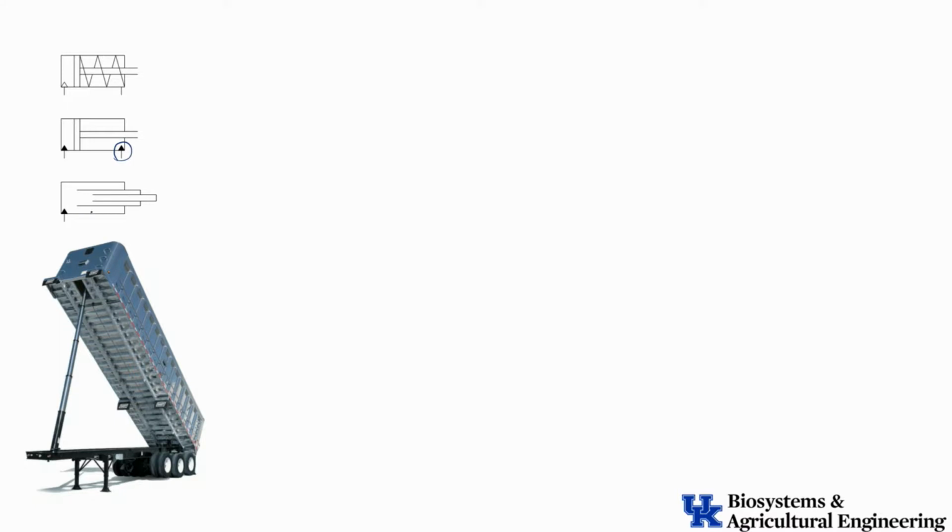It would be way too tall to put on the truck. So what we do is use a telescoping cylinder. You can see there are different diameters of the different sections of the cylinder coming up there. As we lift this thing, we put fluid in the bottom, and it's going to push each stage out sequentially. Obviously, when the first stage is going out, we have the most cross-sectional area. So think of the pressure acting on the bottom of all of those sections, and so we have a relatively large cross-sectional area. So that'll lift a heavier load.